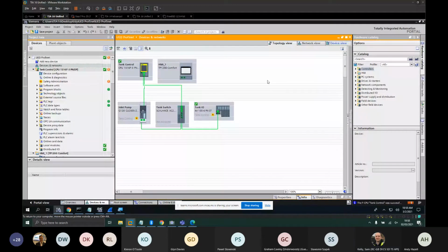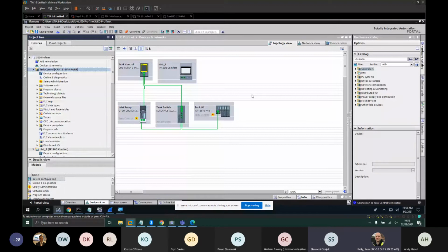Okay. Any questions on that? Yeah, I've got one. Yeah, go for it. Because you increase the cycle time for the Profinet to refresh the data to 256 milliseconds, yeah? Does it not automatically increase the time for the safety, which means previously I had 2 milliseconds and after 6 milliseconds it just tripped. Now I'm actually allowing for 0.7, almost 3/4 of a second before I actually do some safety action on it.